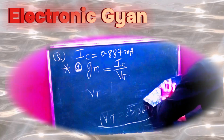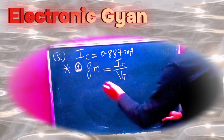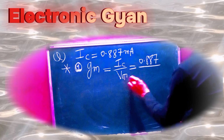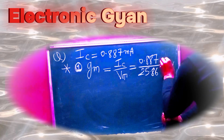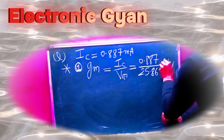Now therefore we get the transconductance as how much? The collector current that we have obtained is 0.887 milliampere divided by the thermal voltage, 25.86 millivolt. So this is ampere per volt. Milli will get cancelled on both sides and it becomes ampere per volt.